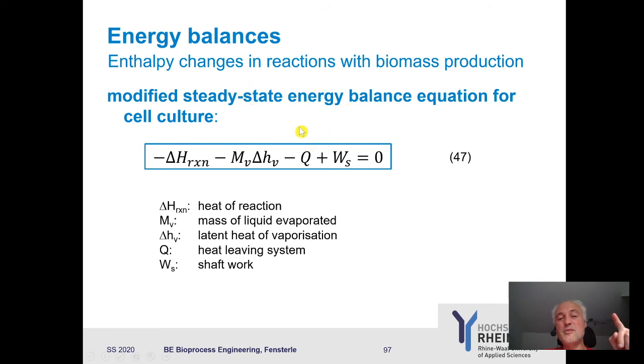In this energy balance, remember, we have neglected sensible heats. There is no extra term for the heat if we have an incoming stream where we have a lower temperature or higher temperature, we neglect that. So you remember that what you have calculated in your exercise example 8 was, of course, only sensible heat changes, because in this case, of course, you had a cooling process. Of course, there it's relevant. But in a real bioprocess, these sensible heat changes don't play a role, because, of course, you don't put tons per second of cold water in and take it out.